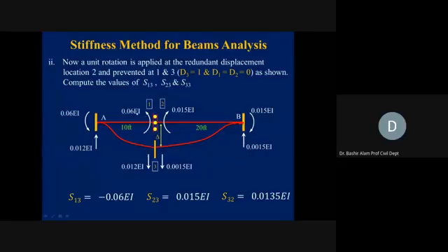How the magnitude, it will be 6 EI delta divided by L square. So L for this side is 10. You put the values in this equation, get this value. Far end, it will be the same amount, the same sign. Balancing couple, it was counterclockwise. This is clockwise. Similarly, for the right-hand side portion, this will be 6 EI delta divided by L square. So L is 20 now. This is how we get 0.015. Far end by the same amount. And this is the balancing couple. Now, unbalanced moment from the right-hand side span was clockwise. So balancing couple is in the counterclockwise direction.